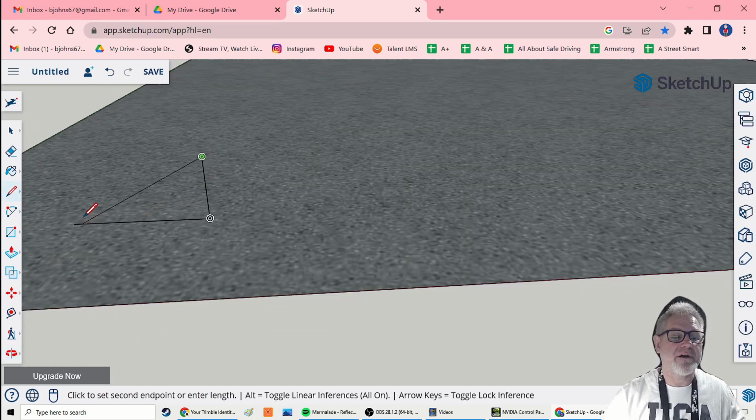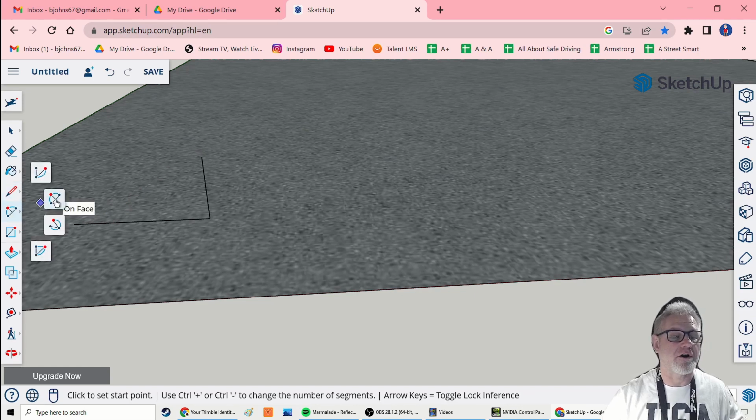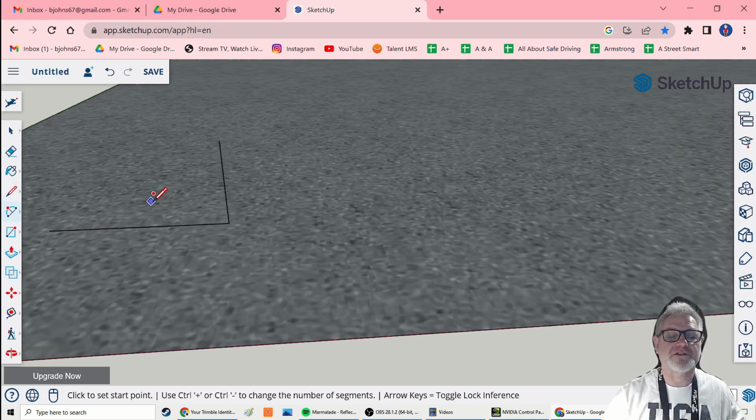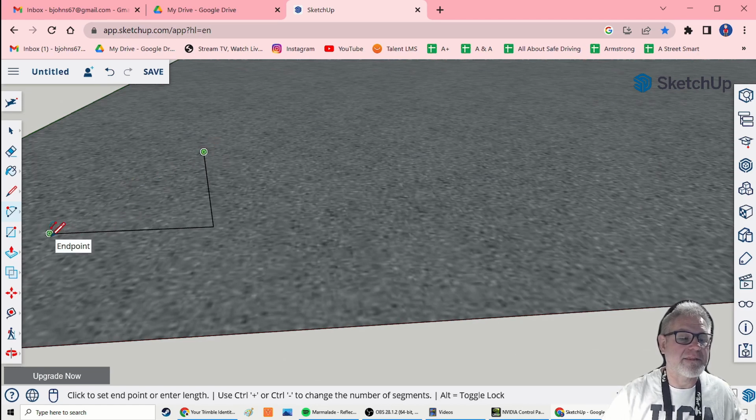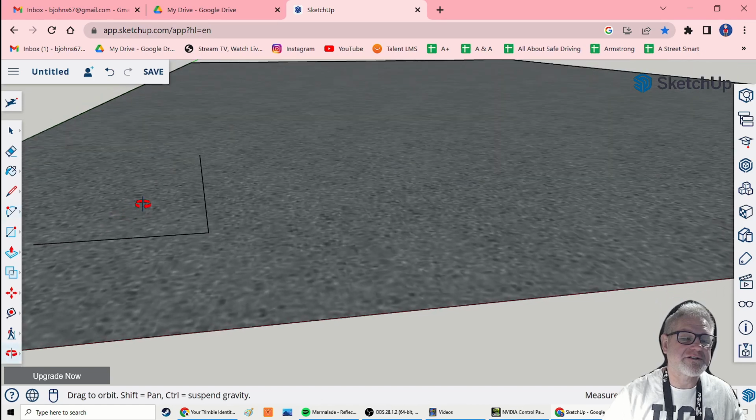Now here, you have the option of making a flat ramp, but we really want it to be curved. And so your best tool is arch, 2-point arch. This part's really fun. I love this part. Click on the top of that line, the left side of this line, and then you can choose how much of a slope, how much of a bend here.